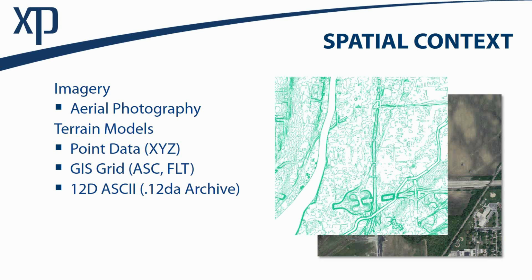And talking with the developers, we may want to look at how we make this a little bit more apparent: LandXML. If you import the LandXML from the File menu, pull it down to Import, select LandXML, you can import a LandXML surface. So really, four different ways of getting that surface in.